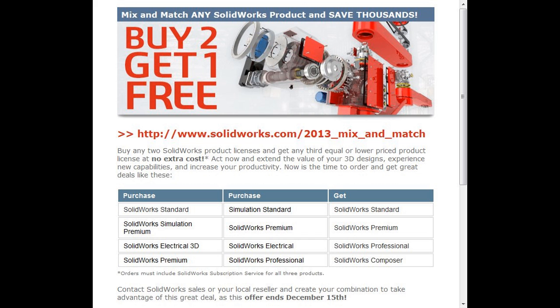All right, here's another question. You mentioned order of features is important. Can you talk about best practices for ordering fillets with respect to each other and the rest of the tree? I was always taught draft early, fillet late, big fillets before little fillets. That's a general rule, but you also have to consider how the part is going to be machined. Can I cut that with a ball end mill, or however you're machining this thing?